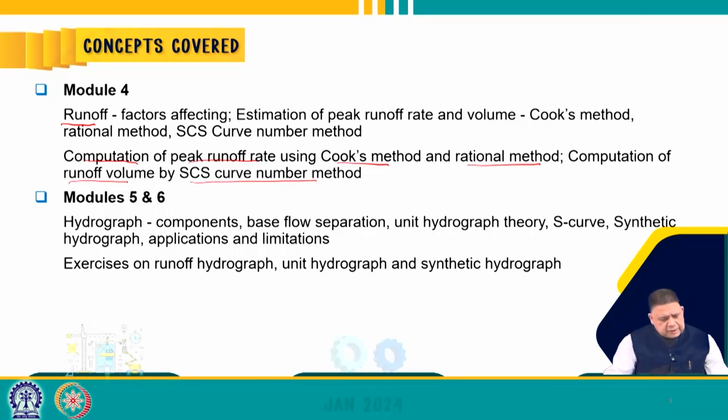In modules 5 and 6, actually these are two combined modules where we will talk about hydrograph, that is the components of hydrograph, base flow separation, unit hydrograph theory, S curve, that is summation curve, synthetic hydrograph and applications of hydrograph theory as well as the limitations of the hydrograph theory, and we will carry out exercises on runoff hydrograph, unit hydrograph and synthetic unit hydrograph.